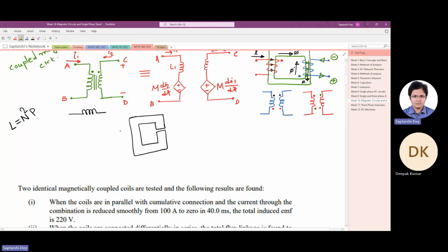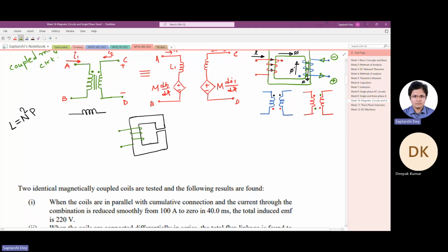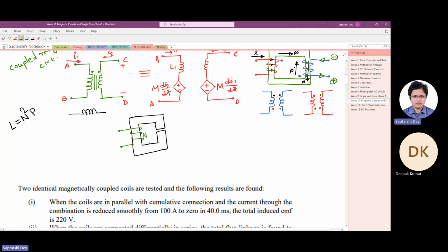intending to operate. Now this has a winding in this fashion. Okay. Now this becomes an inductor. Now what decides the value of the inductance? The value of inductance is decided ideally by the number of turns that you have here of this coil and the geometry of the magnetic circuit. Okay, that decides the inductance, how much inductance you will get from this coil.